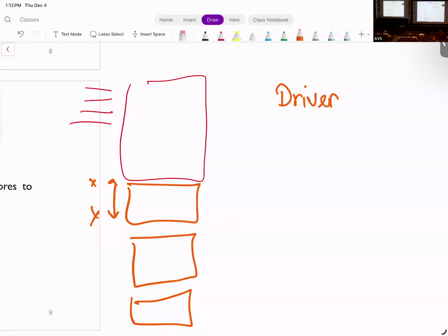Then if you want to read from or write to your keyboard, you call those functions, and at the lowest level of hardware, this becomes a load or a store. So you know how to deal with that. The same story happens here. There are a whole bunch of things happening at the OS level to map the addresses and check those things. You create a device tree and all that, which is separate from what we need to worry about here.